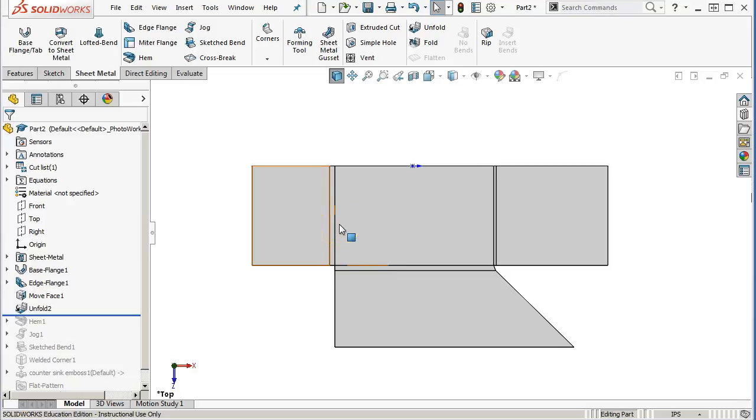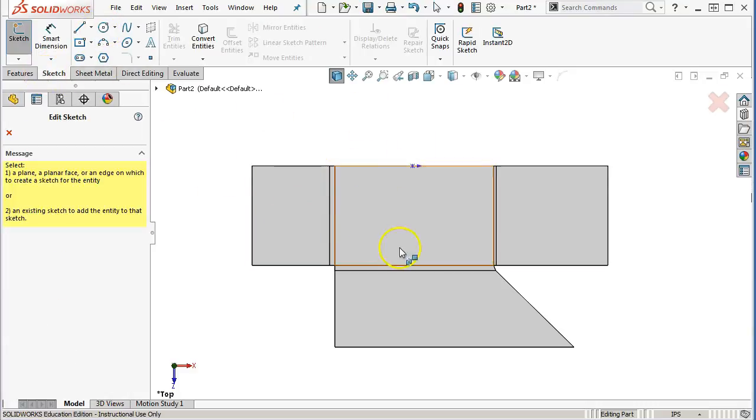I don't have a really good example, but when we rolled the large sheets as opposed to bending, we needed the roll locations and the radiuses of a roll. So, trying to make a shell with like a 120 inch radius or something along those lines, we don't want to see those center lines. We don't want to see the bend lines. We want to see where the radius starts and ends, the length of the radius, and where we can pick up those locations.